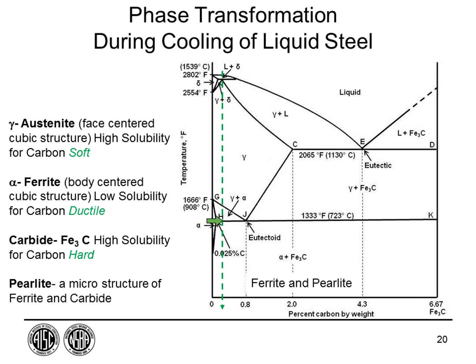As we move further over here, we're going to form more pearlite. Over here in this range, this chemistry will form only ferrite, and the material will be softer if we do that. So these become important to us in terms of this is where we hot roll the steel. This is where we're going to be in the shop when we're working with it.